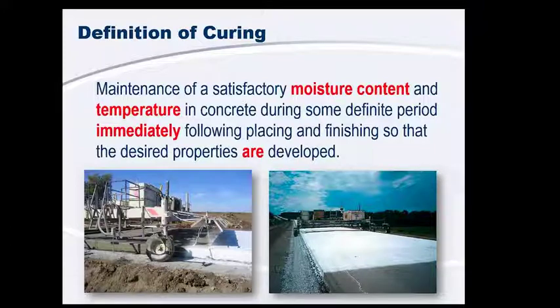the reason for that is when we properly cure our pavement, what we're trying to do is keep our moisture and our temperature within our concrete. The reason for that is that's what's going to help drive our hydration reaction. So when we keep that moisture and we keep the temperature in the pavement, it's helping our hydration reaction, and that's what's going to develop the properties of our concrete that we want, the strength, the durability. That's really going to help make our concrete as good as it can be.